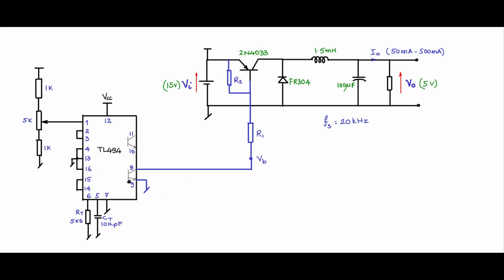When this internal transistor turns on, the collector will be connected to the emitter and VB will be at ground potential ideally. So there is a path for IB on to flow here. 2 IB on flows through R1 into VB and into the ground and completes the circuit.